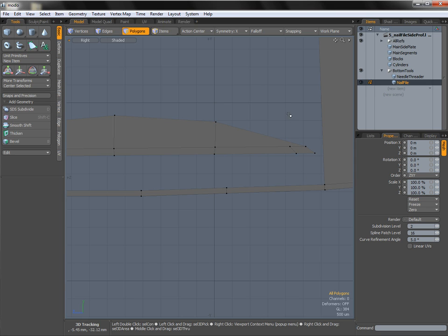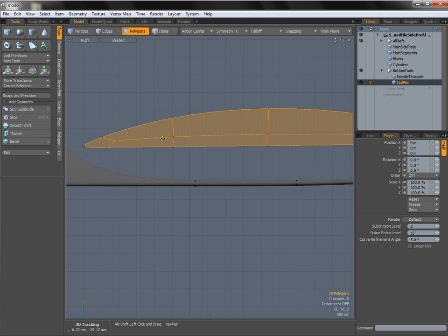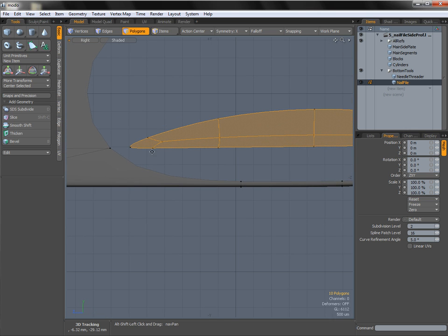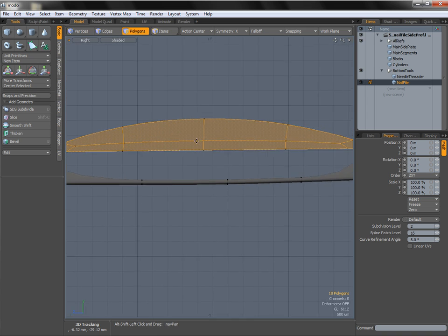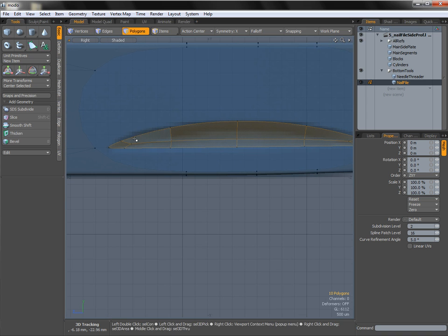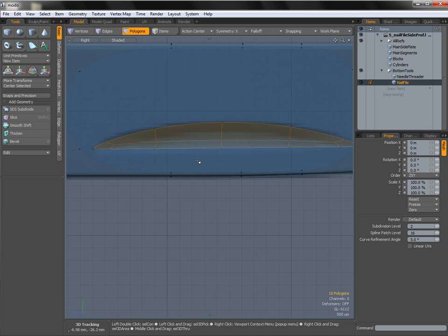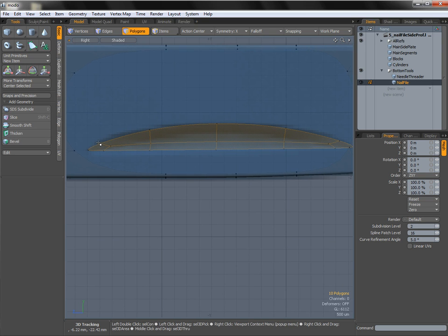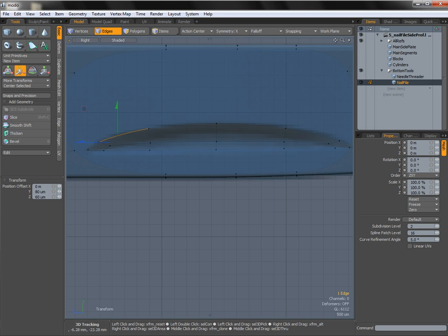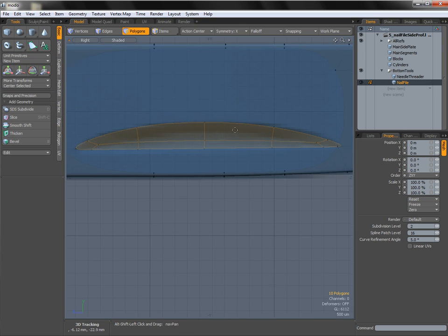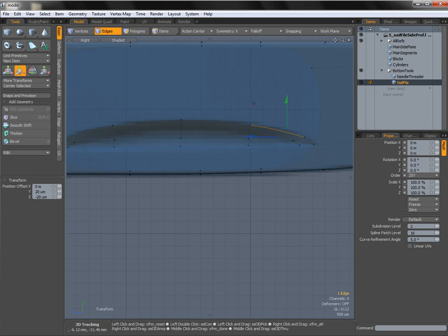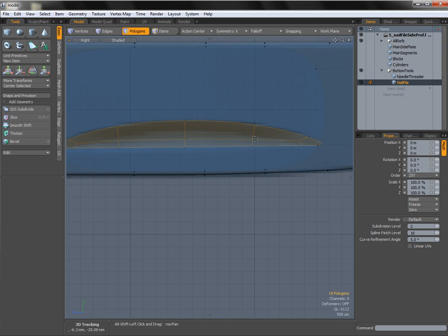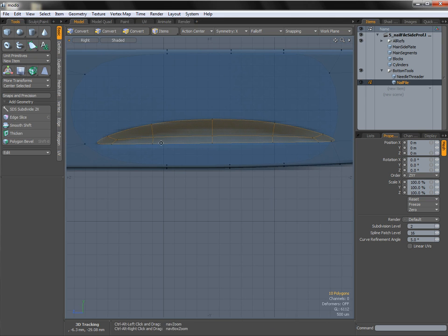It has 4 vertices making it up. So let's take a look at what happens when we go to subdivision mode. So tab, and you'll see that things are actually not looking too bad. They're looking pretty good. So I think for now we'll leave them like that, and then if need be, we can come in and tweak them a little bit later. Now as you can see, we're obviously not following the ref perfectly here, so I'm going to grab this edge and just pull that up a little bit. Double click, and we'll do the same thing over here. I'm just double clicking the mesh after I move it just to see really what's going on. That's pretty close. I'm pretty happy with that, to be honest.